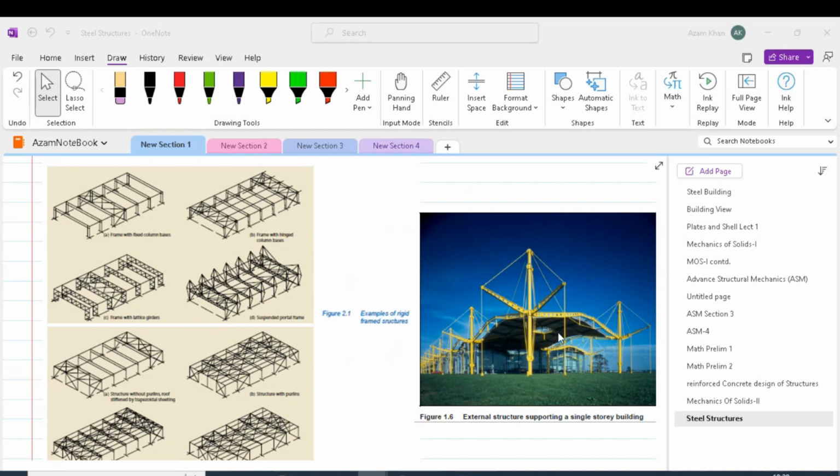The suspended structure can be designed by extending the column outside the building envelope, as illustrated in this picture. Suspended structures accomplish long spans, although the suspension cables or rods also penetrate the building envelope and can be obstructive to the use of external space.